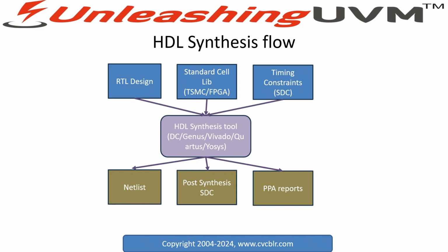Design constraints, but some people tend to call it standard design constraints, primarily the non-Synopsys EDA vendors, because it's not really a standard, as in, it's not an IEEE standard. We'll talk about that in the next couple of slides. So the SDC, standard cell library, and the RTL design, these are the three inputs.